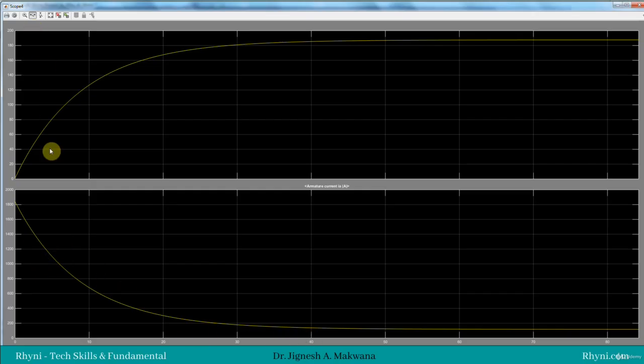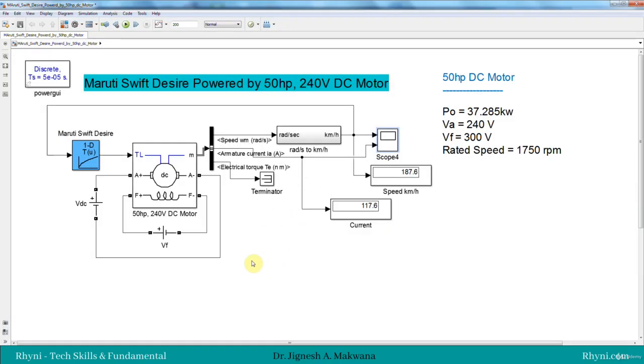So first we need to find the rated current. We must limit the current to the rated current, and we can also use the speed control system with the current control. So here we require the current limiter, and then we can see the actual performance, because this is not actual performance. This is not going to happen in any motor. All motors will require initial current control to protect the winding. So we will add the current control loop that we already discussed with the help of a voltage control source instead of this DC source.